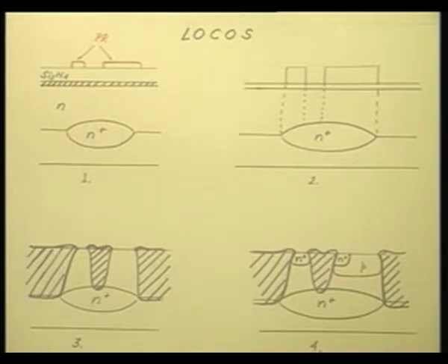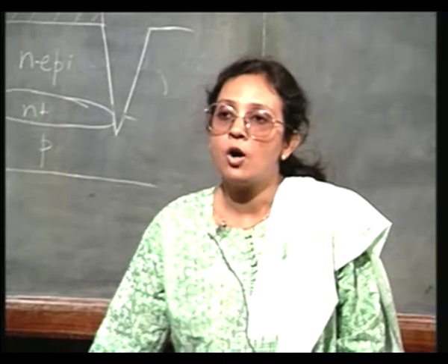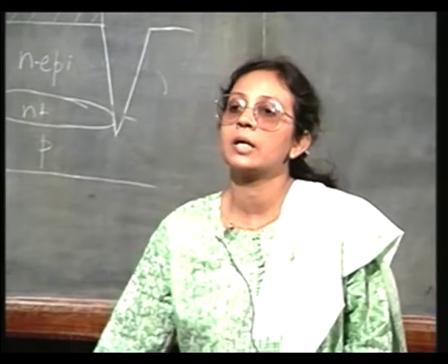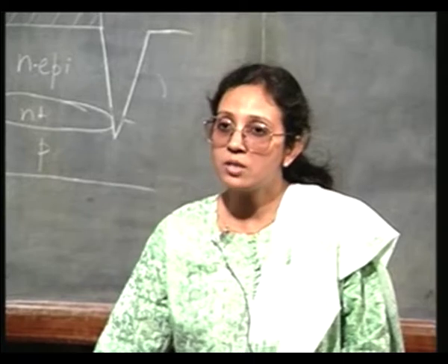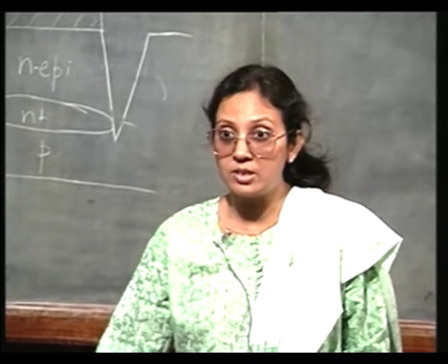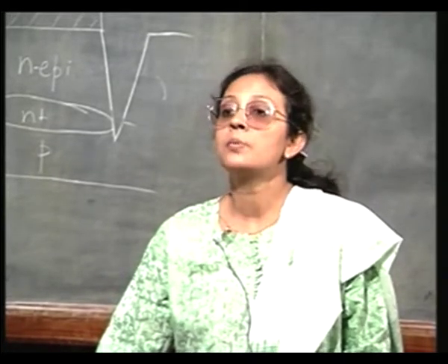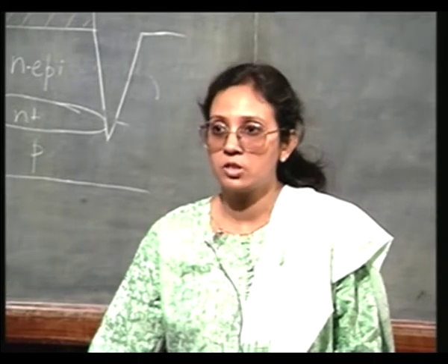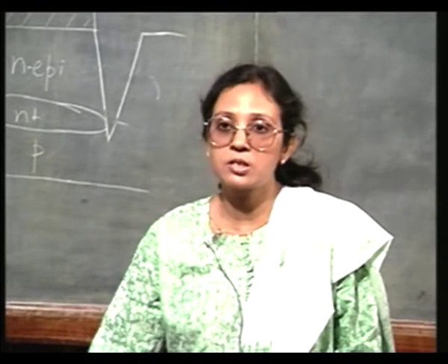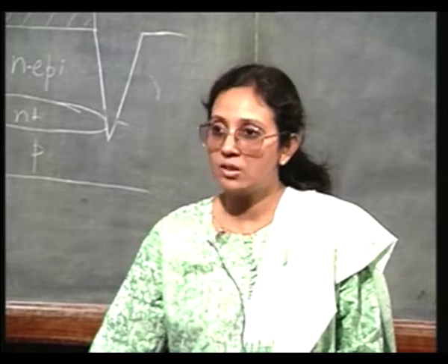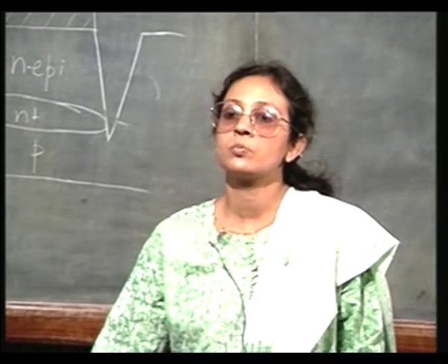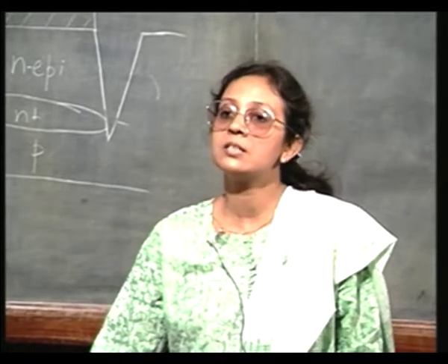The key factor in this is the term local oxidation. We want some regions of the semiconductor to get oxidized, and we want some other regions, the active region for example, to be prevented from oxidation. We do not want oxidation to proceed in the active region, we want oxidation to proceed in only the region surrounding the active transistor.